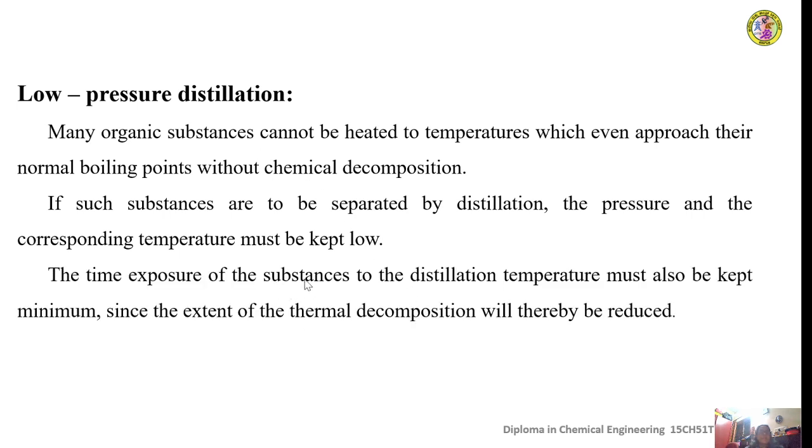Also we should take care that the time of exposure of the substances to the distillation temperature must be kept low, in order to see that the extent of thermal degradation or thermal decomposition is kept at as low a value as possible. So that is how we can separate the organic substances using a low pressure distillation technique called the vacuum distillation technique.